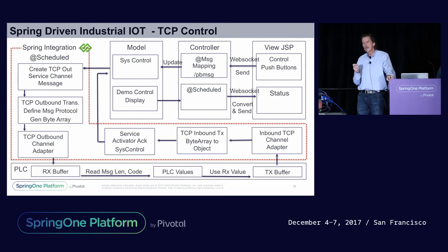And the very first thing, you have to develop kind of your own protocol with this, because you've got to specify for the controller what's the length. So that's the very first field it's going to see, the length. And then a message code to tell it what those bytes mean. And so you will break that down in the controller.